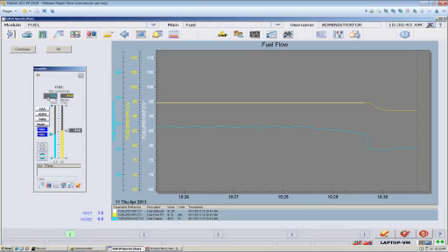Now, most likely what's happening is the actuator stem is moving, but there's sloppiness between the actuator and the valve. I see this most often in rotary valves as opposed to sliding stem valves. It can be a problem in either, but it happens more often in rotary valves, especially if the connection between the actuator and the valve is a bolted square shaft. Sometimes that square shaft gets a little worn out and turns into more of a bow tie shaped shaft. So when the actuator moves, the valve gets left behind until that sloppy worn out part gets worked through.